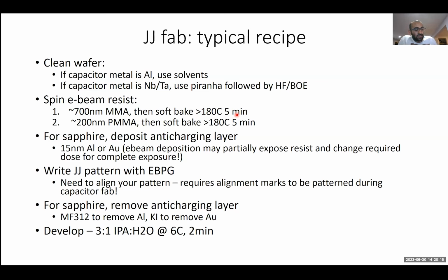But as long as you maintain your bottle of resist well and make sure it doesn't dry out, it can last well beyond its expiration date. As far as temperature, humidity, and environmental conditions, they all matter, which is why we store our resist bottles in the clean room, which has well-controlled temperature and humidity at all times.